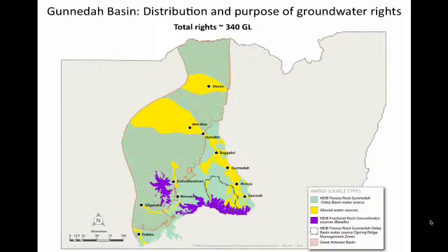The purple areas represent the shallow basalt caps and flows that overlie the porous rocks in the southern areas on this map. The yellow represents the shallow but extensive alluvial deposits in the area. The main deposits are the upper and lower Namoi and the Gunnedah, with some smaller areas of alluvium along the Macquarie and Castlereagh rivers. Alluvial systems are made up of sands, gravels and clay lenses and often contain high quality water with very high yields and are targeted for water supplies.